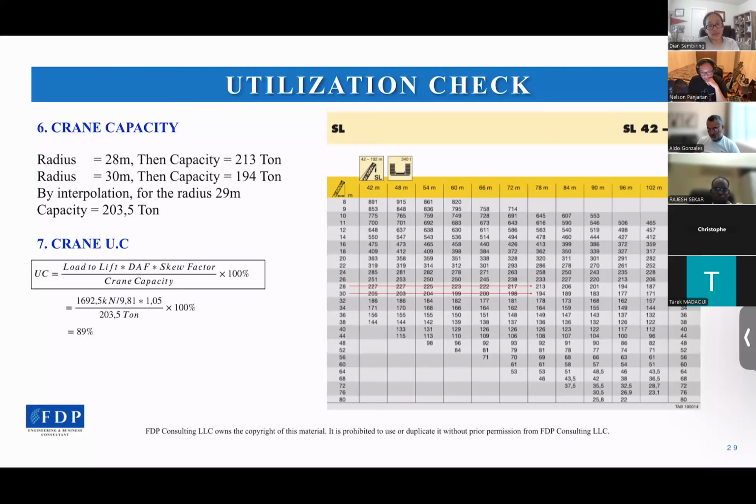and also the lifting gear that you have to use. Either you use a spreader bar to ensure that the load distribution is equal, or you don't need to use the spreader bar for your lifting operation. And then center of gravity for your crane, and also ground bearing pressure. So if you understand these 3 components, we believe you will be more expert, and more qualified for safe lifting operation.